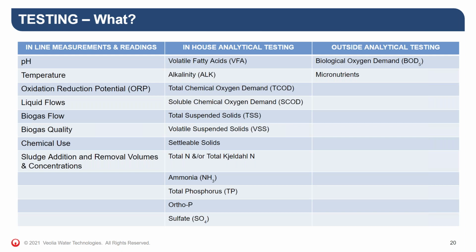You need to know the total and soluble chemical oxygen demands, the total suspended solids, volatile suspended solids, settleable solids, the nitrogens, TKN and ammonia, phosphoruses, and sulfates.